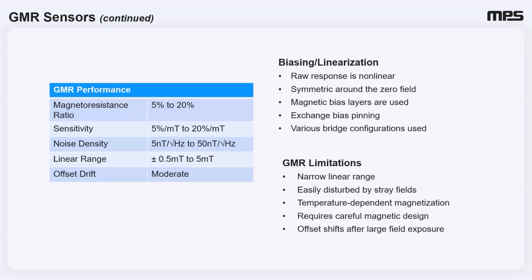There's also, we're going to start to see this recurring theme with the MR sensors, which is the better the sensitivity they are, the more fragile they become in real motor environments. And that's because when you have the higher sensitivity, stray fields affect them more. Again, I simplify these things to keep this within a 1 hour webinar, but there are systems built around all of these raw sensors to make sure that we try to cancel out all the limitations.